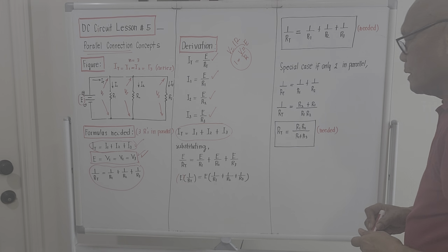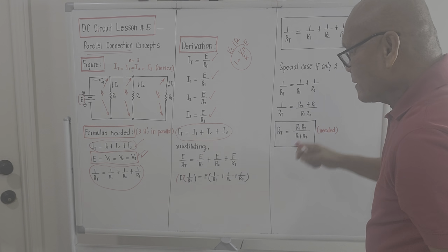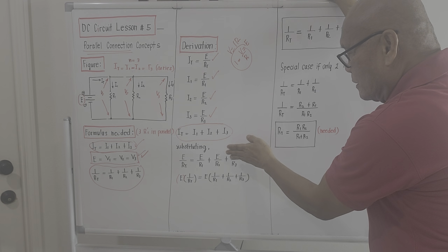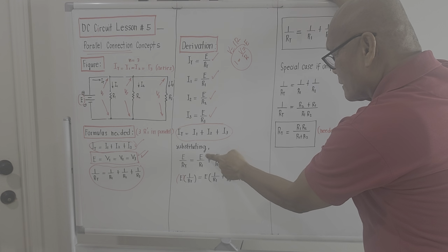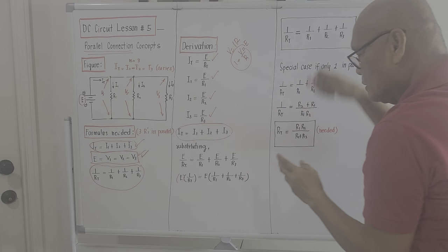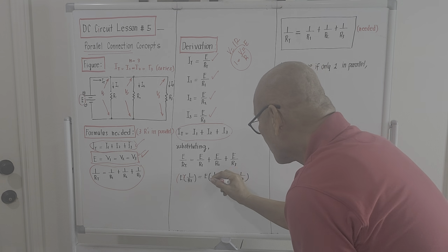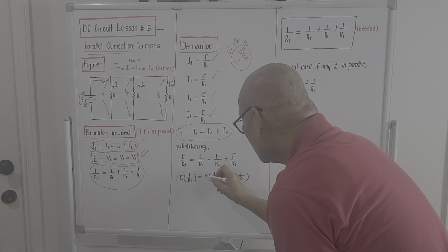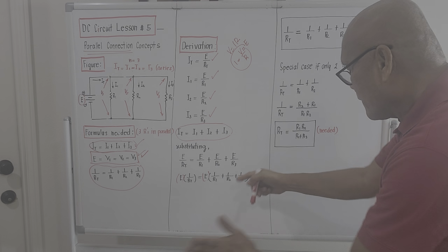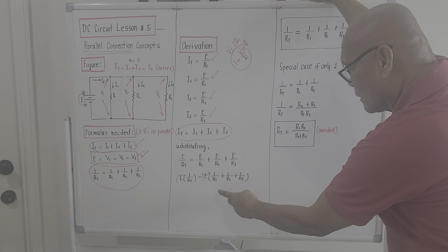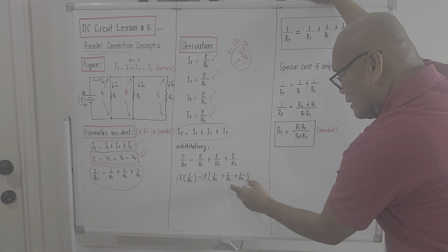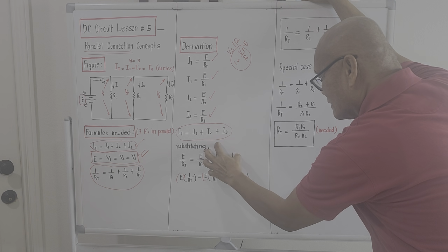And this should be equal to, again, on the right hand side, this is now algebra, right? If we observe the numerator, each individual numerator contains an E, and actually we could factor out. That's algebra. So again, we brought out E. It's a common factor, right? So what will remain on the right hand side on this portion here will be 1 over R1, 1 over R2 plus 1 over R3 in a closed quantity. The product of all of these times E is just this.